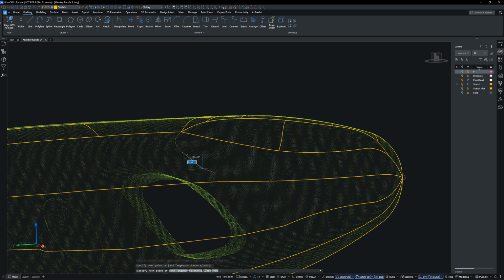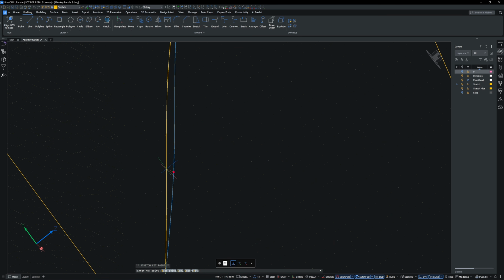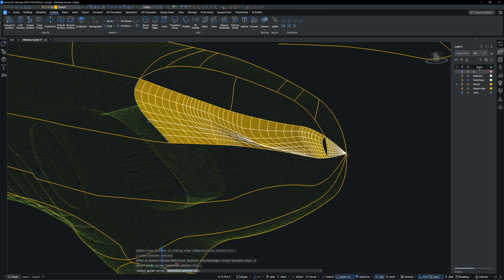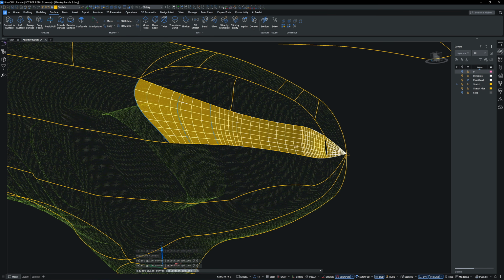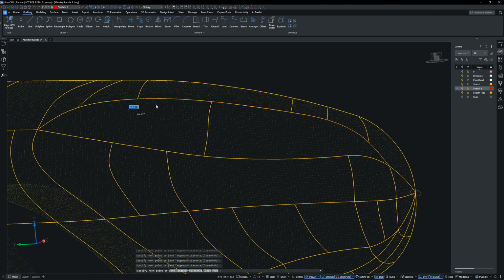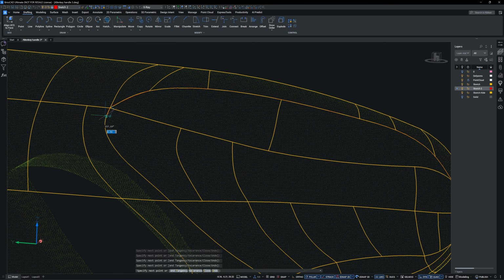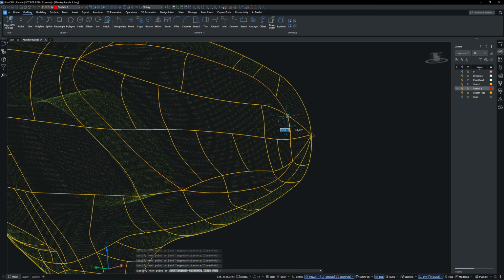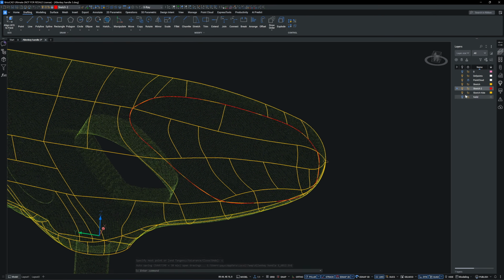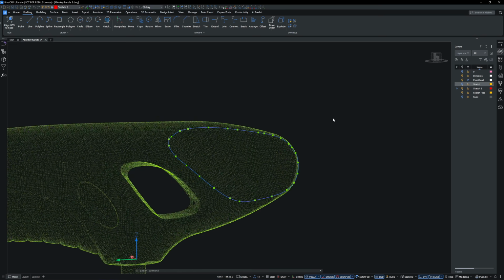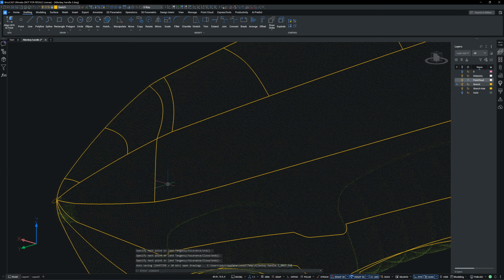Once the curves are complete, recreate the splines as a continuous curve, then break it again at the boundary intersections. This approach creates tangential continuity across the surface segments. Here, I'm retracing the spline with the curve shown in red. The result is a smooth, continuous curve that can later be broken at the boundary points. The broken spline will retain its shape and continuity.